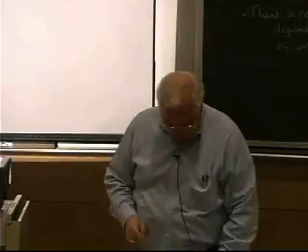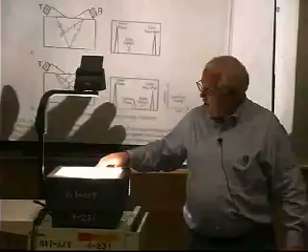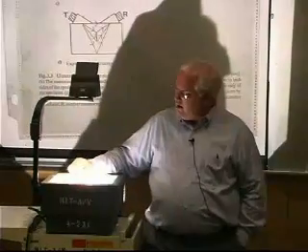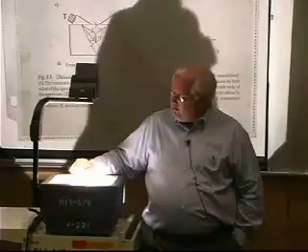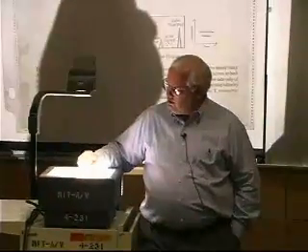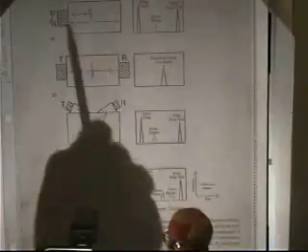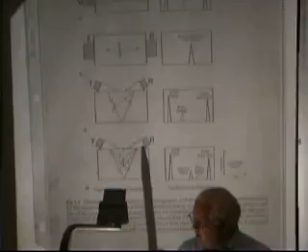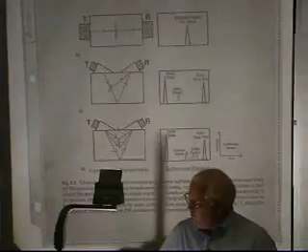Actually, I guess I have another picture here showing pitch and catch. So here's the initial pulse, the echo off the rear wall. If you have a defect, it'll be somewhere in between. It takes shorter time to traverse that than to go all the way across. So on your time base, you'll see grass grow in the middle with a defect. Here's the pitch and catch, where you have a sender and receiver. Okay.